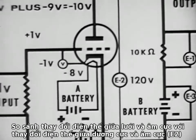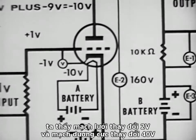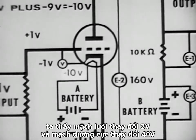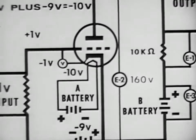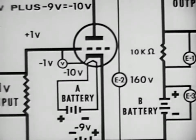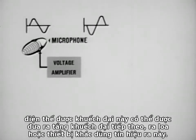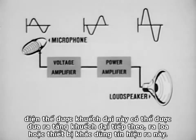Comparing the voltage change between the grid and the cathode to the voltage change between the plate and cathode, we find that there is a 2-volt change in the grid circuit, and a 40-volt change in the plate circuit. We have thus amplified the signal voltage 20 times. This amplified voltage is applied either to another stage of amplification, a loudspeaker, or some other device which uses the amplified output.